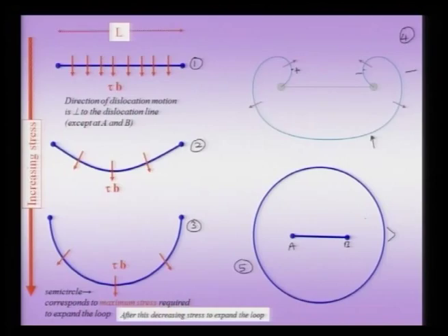That means the same set of dislocation pinned segment can keep on operating again and again, creating such loops. So again I applied shear stress, then this whole process of bowing of the dislocation line can occur, but now we have to remember this bowed segment has to interact with the stress field of the additional loop which has been created. That means the second time I operate the same pinned segment, a double-ended Frank-Read source, I have to apply an additional stress as compared to the first time around. But nevertheless, I can keep on operating this Frank-Read source and therefore create more and more loops.